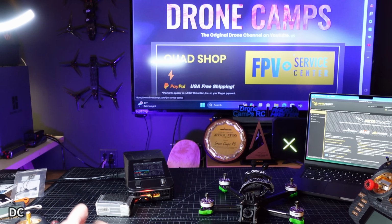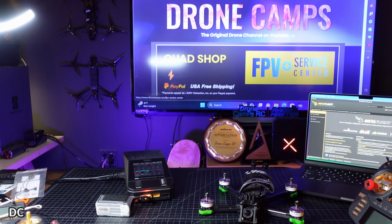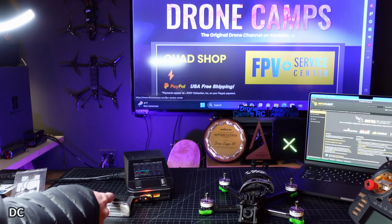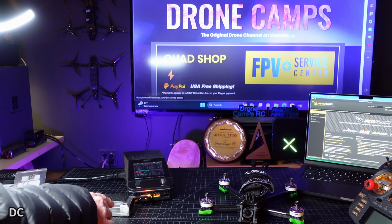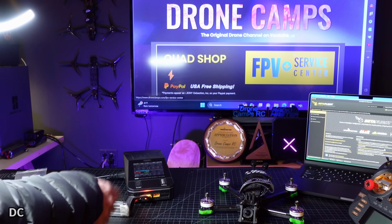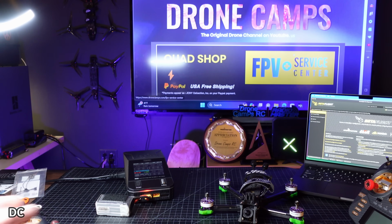So what you will hear, sometimes, if you don't have music playing or the TV playing, you actually hear a nice low fizz. And that is air escaping from one of the cells because everything in there is heated up and gas is escaping. So if you hear that, disconnect it at once, take it outside, whether it's hot or not. If you hear that fizz and you kind of smell something as well, smoke will come next and then fire. So it's very important that you look out for that fizz and that type of noise.